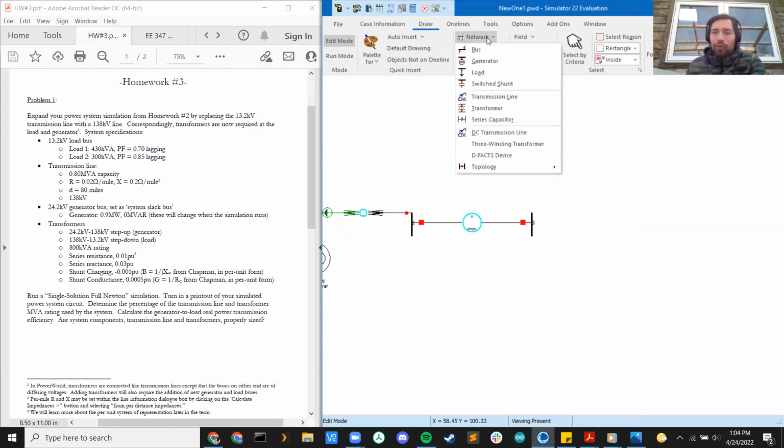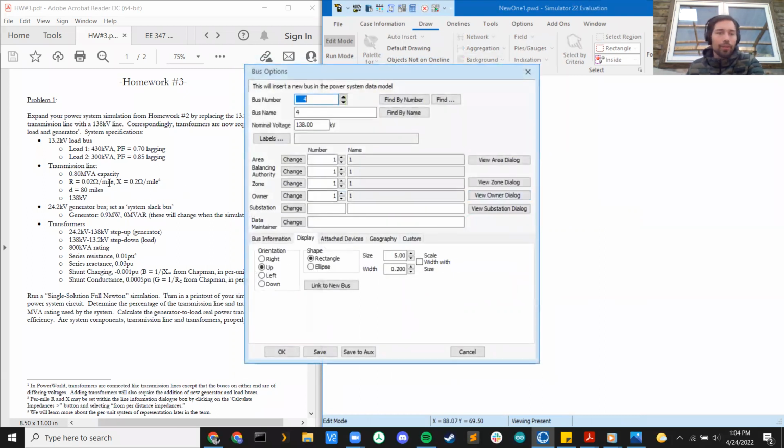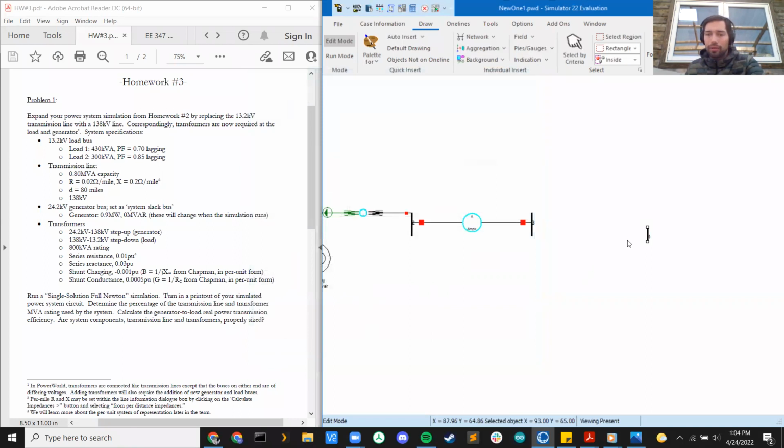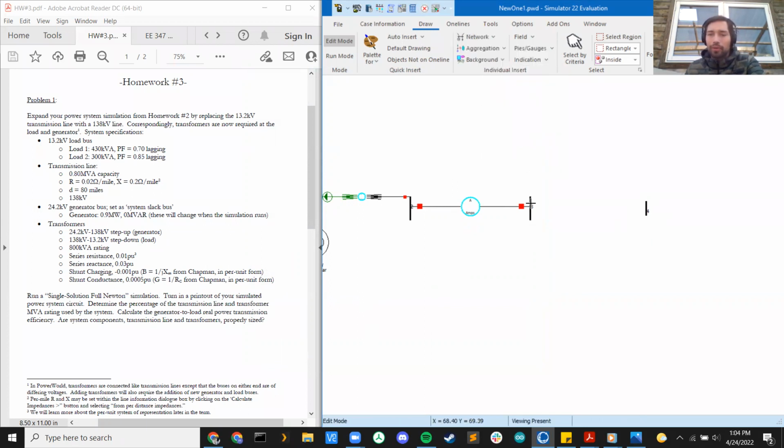We are going to add one final bus. This is going to be our load bus. It's what our 138 is going to be stepping down to via the transformer. So this final bus up here is a 13.2 kilovolt load bus. We again only need that here to make this work. Now, not sure why each of these have been made to be a different size, but we'll make it work. And then here, all we do is, again, put a transformer between them.